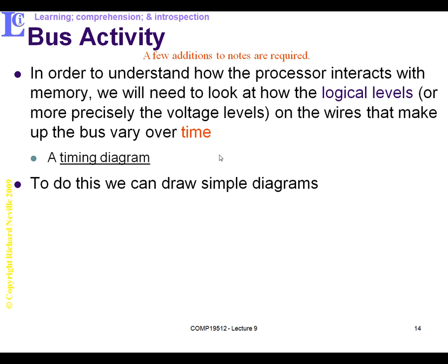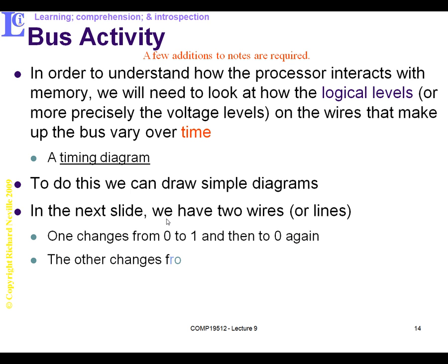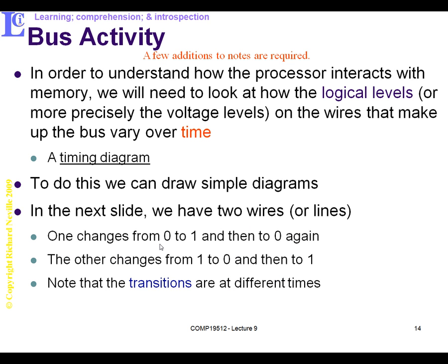We're going to look at a relatively simple timing diagram, on the next slide, where we have a number of wires and we're going to change the values on these wires from particular values to another value. One of them will change from a low, a 0, to a 1, a low to a high, and the other will change from a high to a low. It may change again afterwards. When they do change, the explicit region on the x-axis where they change from one level to another is called a transition. Let's go and look at these diagrams in detail then.